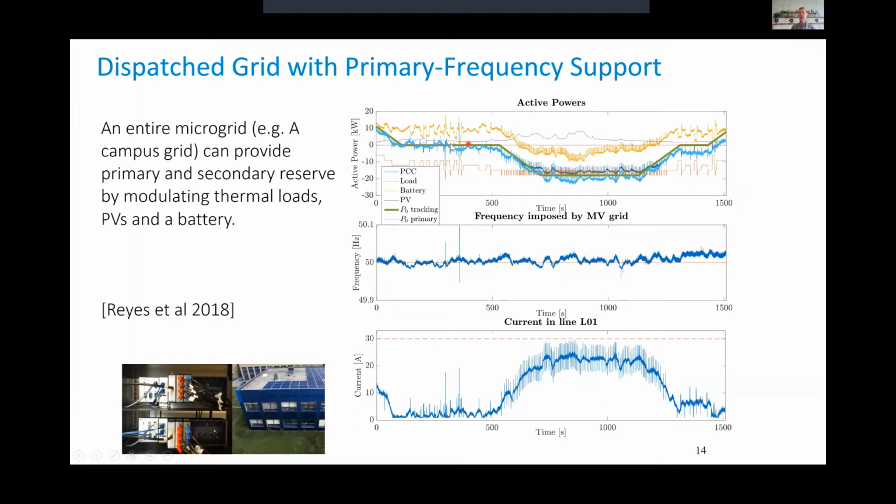Of course, this green line is highly compressed in time. A power profile of 0 means here you say my grid is energy neutral, truly energy neutral. Very oftentimes when you hear that somebody has a building that's energy neutral, it just means that over the year, the amount of kilowatt hour that they consume is equal to the amount of kilowatt hour that they produce. But it's not really neutral, in the sense that if you produce and consume at different times, you still need a grid. Here, the idea is to control at a very quasi-instantaneous time scale the power exchange.